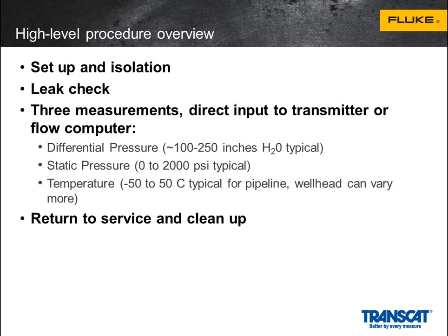The key thing to note is that the 2 pressure measurements are at very different scales. Differential pressure is frequently just a couple hundred inches of water, whereas static pressure is anywhere from 0 to, or even vacuum, up to 2,000 psi. And so frequently you'll need different ranges in order to do these measurements. There's also a temperature measurement. Pipelines tend to be in the ambient range, whereas wellhead temperatures can vary quite a bit depending on how deep the formation you're pumping out of.